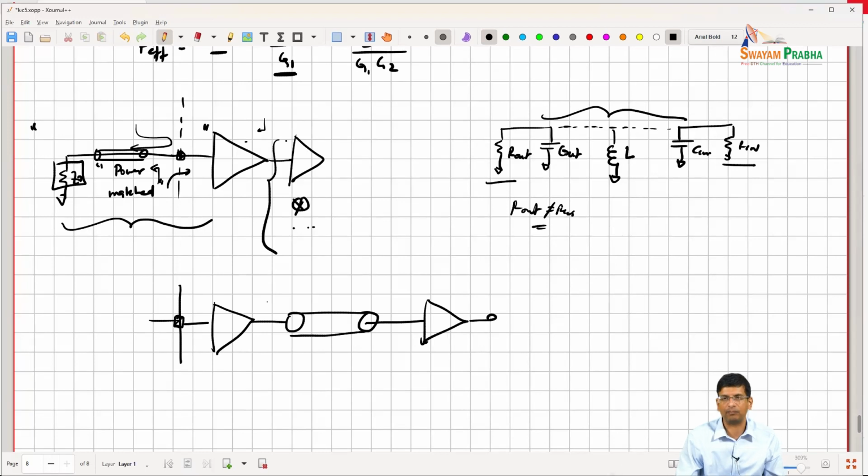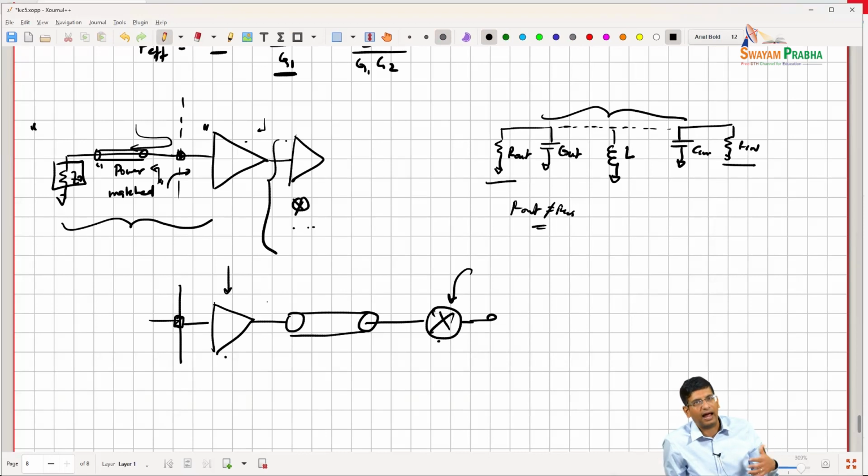And just from a practical perspective, this block is being designed, this block is being designed at the same time, right? Let's say, for example, that all the amplification is in one stage, and we'll say that this is a mixer, right? And as they are being designed, we don't know where they will be placed in the layout and what the interconnect between them will look like. Then it makes sense for both blocks to be designed to Z naught.